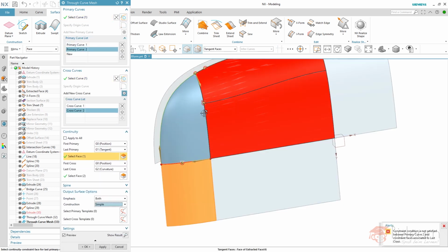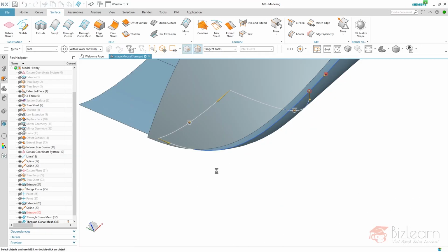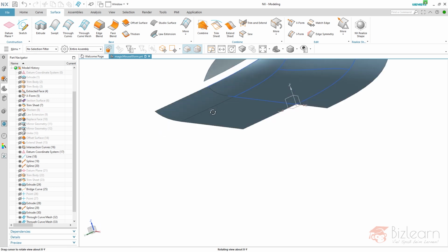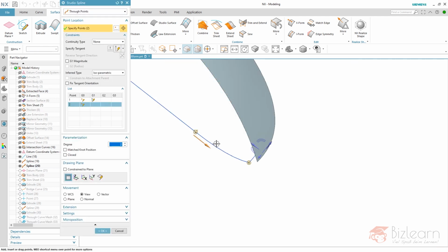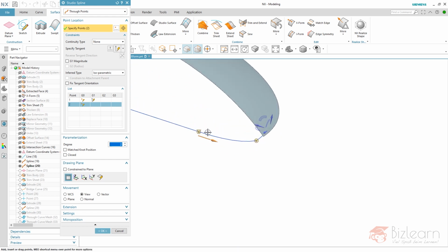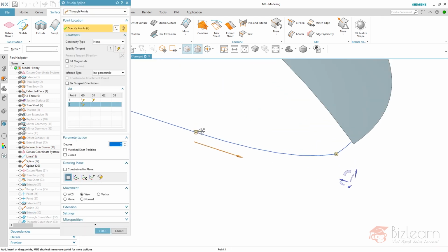And we have an issue here. There's something I guess I have to redefine. I can finish this, but it's not perfect. There's something we can do within here. I forgot. It has to be curvature consistent. Maybe you have recognized I forgot. It's just tangent. That's a problem. The surface cannot be curvature consistent if the input curve is just tangent.